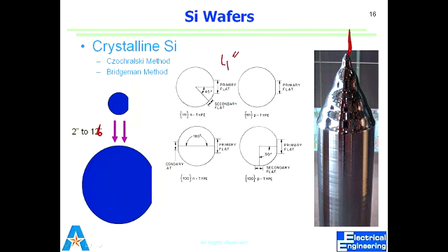Once you are given a wafer, there's no information in the wafer. It's just a shiny disk, nothing written on it. You should know how to tell what kind of doping is in that wafer, and what the orientation of that wafer is, from the flats. It will always have a flat. More often, we hold that wafer from that flat region, using tweezers.